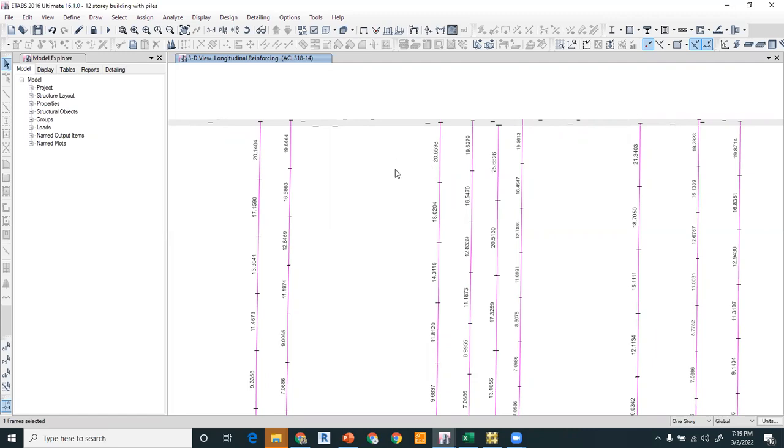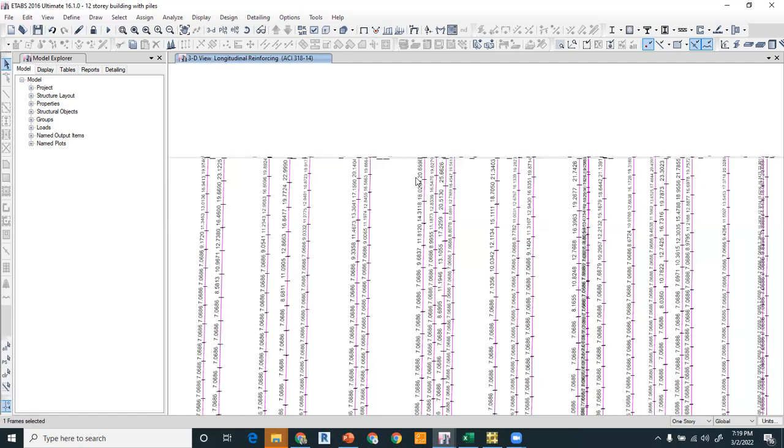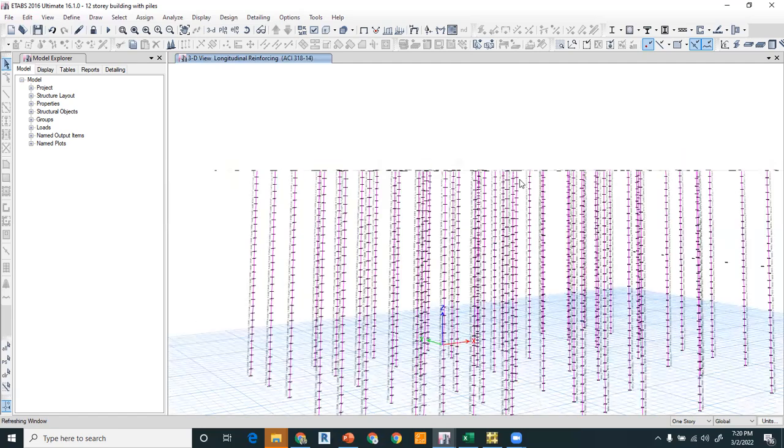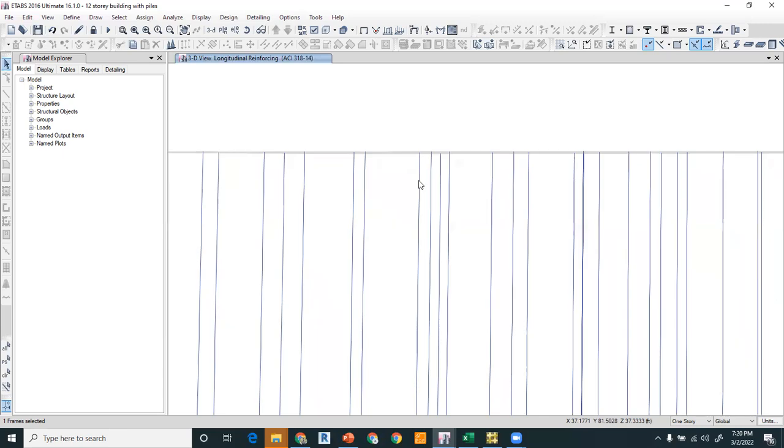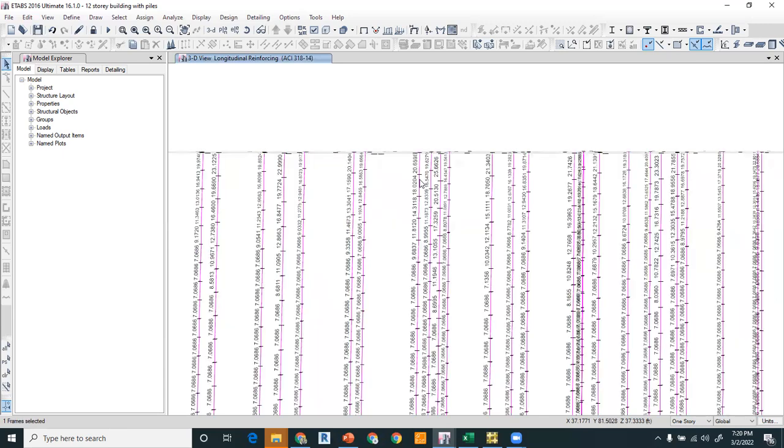But if there is no fault, or the area in which there is no significant earthquake in the past, you can design your piles only for the gravity loads, because you will be thinking that if the earthquake occurs, there are unbalanced moments coming to the structure, but the unbalanced moments will be taken by the raft and the frame structure, and you have designed the piles for the gravity loads. So we'll do it for both cases.